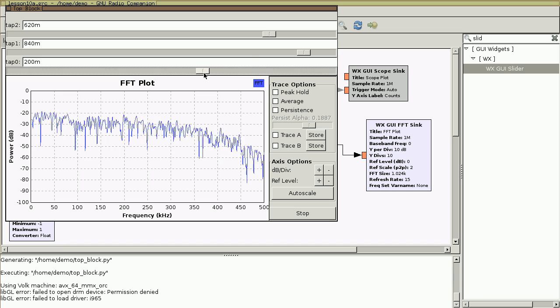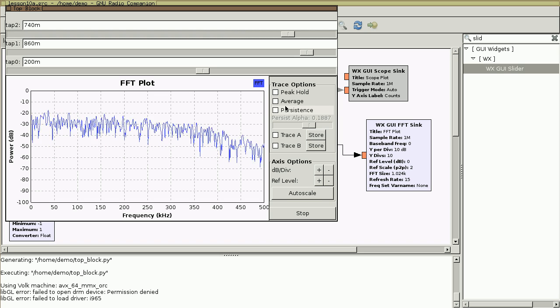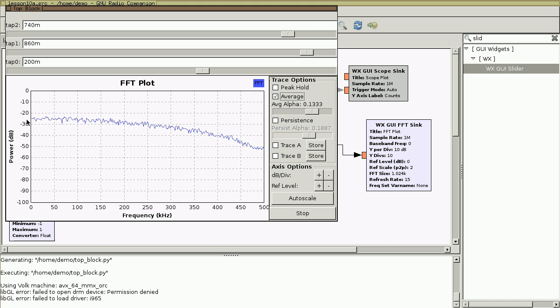Look at this. If I set things like so, it looks a little bit reminiscent of when I only had 2 taps here, except I have a longer sort of gradually sloping transition. You might think of it that way. You can change the frequency characteristics, the frequency response of this flow graph by adjusting these taps, or I might call them coefficients.